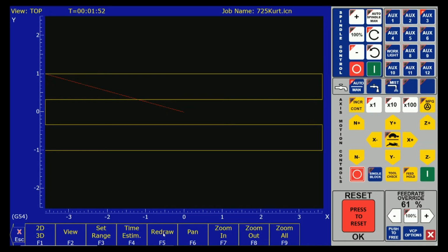This graphing is part of our crash mitigation. We're going to take a look at it right now. And the reason I call that out is because I need to look at it and glean information from it. I'm not just going, ooh, yeah, that looks about right. It's starting left and ending there. What I want to do is, where is my WCS? So I just hit a keyboard cursor, and it brought up these crosshairs, and it defaulted at X0 and Y0. So right there in the center is where I put the WCS on my part.